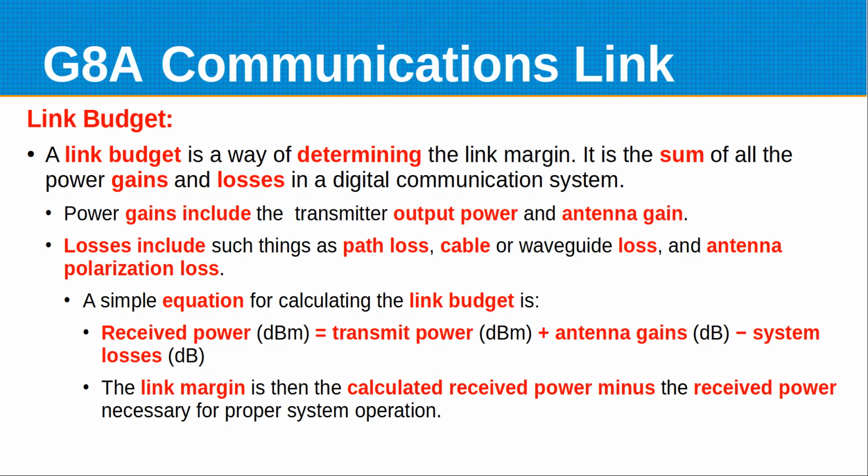In their little example here of the equation, you take the transmit power. So let's say you're operating at maximum power, 1500 watts. So that's 61 dBm. You've got really long, 20 some odd element Yagis. Let's say you got 20 dB of gain. You put four of them up, you're up to 26 dB gain.